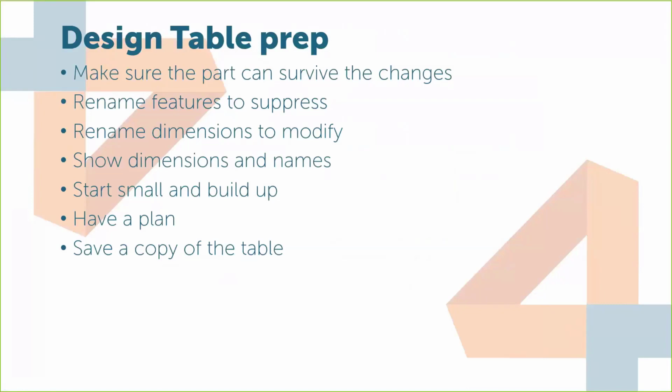Again, have a plan. Now, specific to design tables, save a copy of the table. I'll show you how to do that, and if I forget, I've got a screenshot of it in my last slide. I've seen many cases where the design table is the design. It becomes so complex and so powerful that it really is more important than the CAD model to some extent.